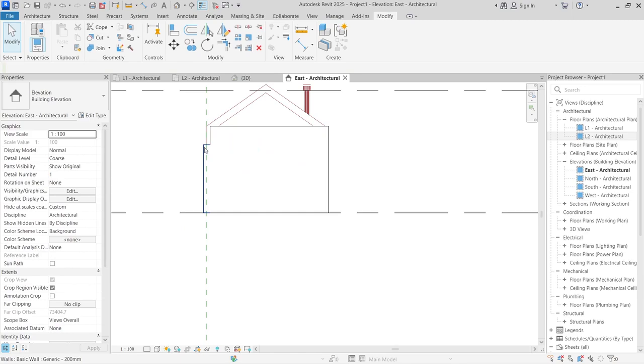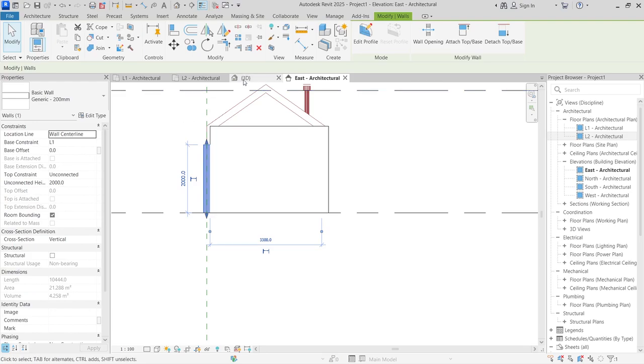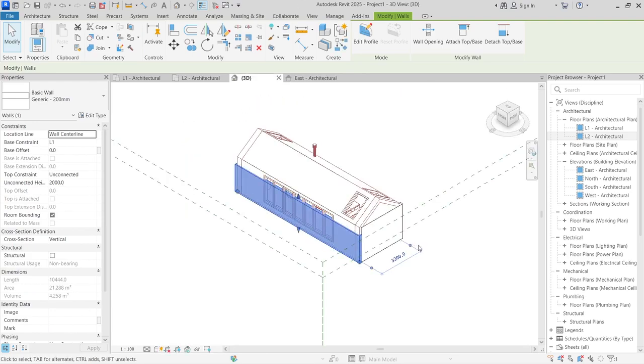and now we have the height of the building. You notice that somebody here hasn't taken that dimension, and should have pressed tab. If you hover your mouse over a wall on Revit and you press tab, it's going to select all the walls, but I didn't do that before I changed the dimension of this one, so that's why this guy was left out. So I'm just going to select this one and make sure that everybody else is selected.